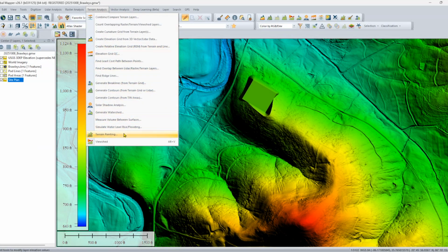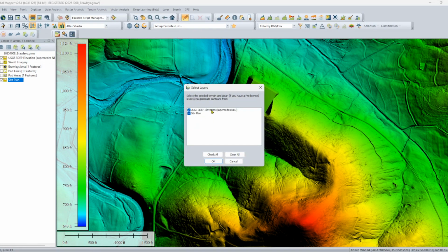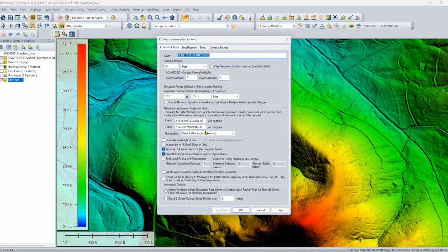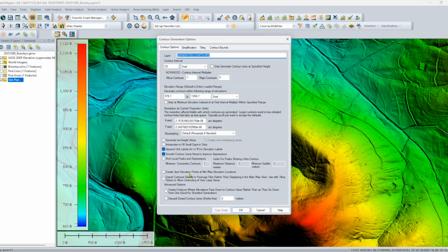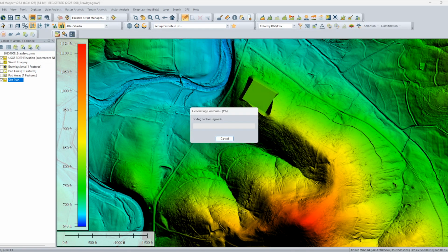Before I start drawing the road line, I want to create some contour lines. Contour lines are a great way to visualize the terrain. I'm using 25-foot intervals, so I get a good sense of the terrain without making the map too busy. But it has also another purpose. This way I can keep the alignment within a reasonable elevation range when I draw the road line.